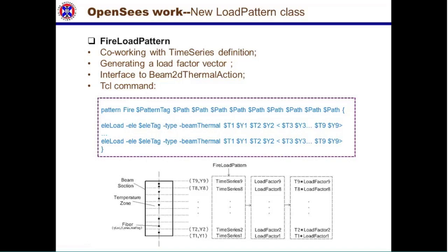So you really need a full definition of all these points over the full length of time of the fire that you want to model. So this fire load pattern command allows that. We can define a temperature time curve, which is what we want for the fire analysis.